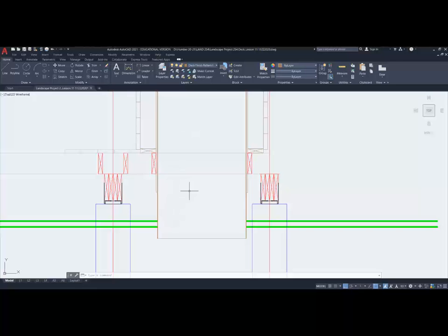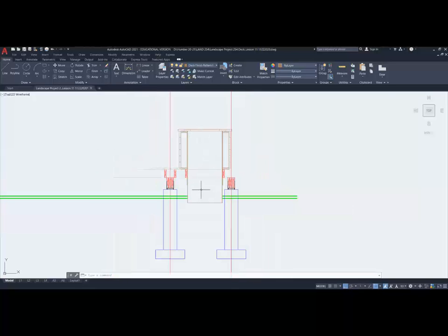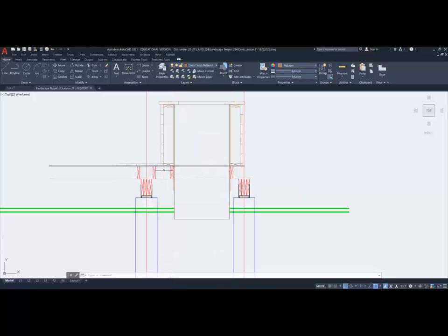Now you've got to be careful as the soil gets loaded. What's going to happen is it may push out some of the sides. Sometimes we'll take this framing and extend it lower through the deck so it actually extends down. And that's an easy thing to do. You just take that framing and bring it all the way through and cap it at the bottom. It all depends on the size and the weight of this, but that's something the builder can do on site unless you want to make sure that it's built in a certain manner. Other times they may actually pack the grade up a bit, but we're near columns and we want to make sure we have 6 to 8 inches of concrete before we get to the actual beams that we have on either side. So this is just one technique. And yeah, it may blow out a bit, okay.